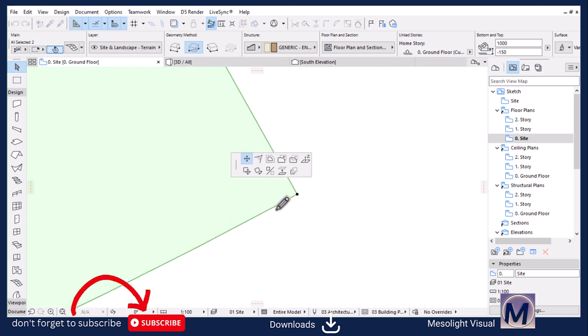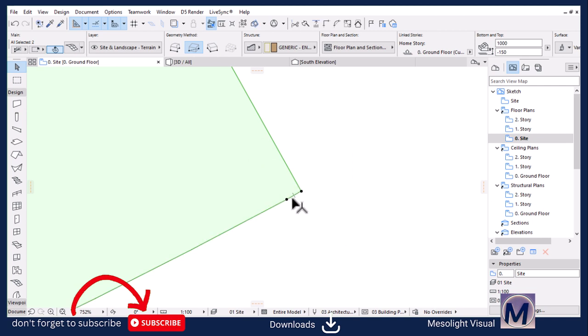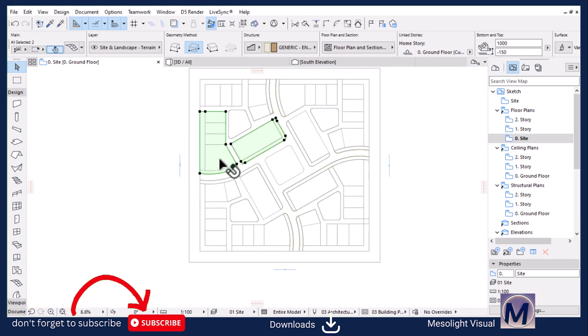Let's see here. I think we need to get rid of this point, or we can, I don't think we can achieve it. You see, it will give us a lesser number because it's being guided by the distance between these 2 points. So the best way is to get rid of the point like that by moving it to the other point, and then you can now fillet without having any issues. Perfect. I think we are okay.